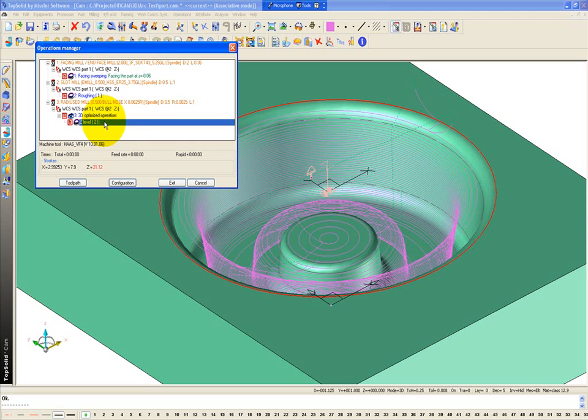Now, the performance of this will vary based on the different machinery that's out there, so you have to do some test cuts to find out which settings work best for you. Also, this arc filter only works on toolpath that are cutting in a standard plane. So the Z-level toolpath works because it's cutting in an XY plane. If you did a parallel plane machining that was cutting through the XZ plane or the YZ plane, you could also apply arcs there as well.